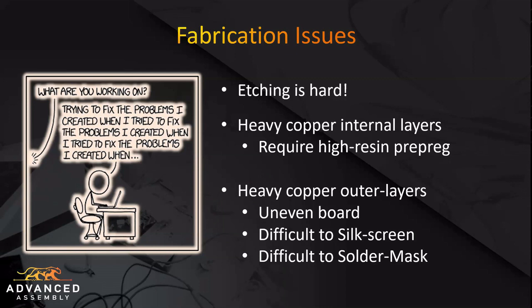At least with pulse plating, you're going to get a more even layer of copper plating across the panel from edge to edge, as opposed to DC plating, where you typically build up heavier copper around the corners if you're not using thieving properly.